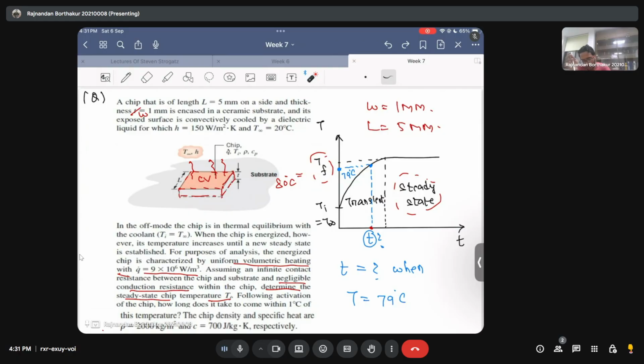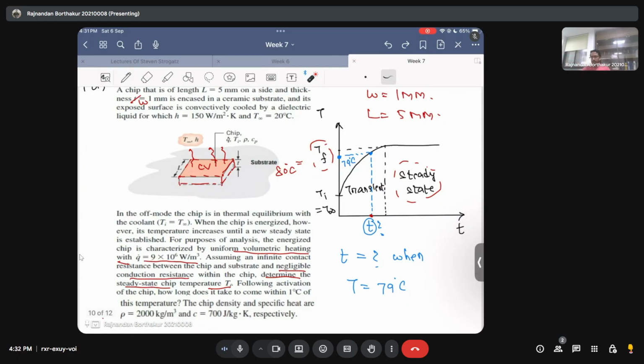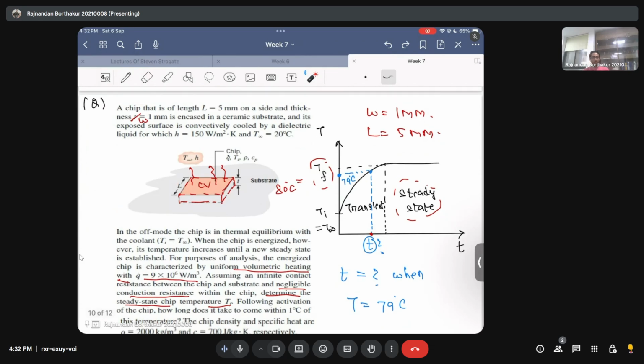All right. Then this is what we did. So I didn't touch one concept, which is known as the semi-infinite solid, which is another case of a transient body. But here, as I said, in case of a semi-infinite body, you cannot neglect the spatial variations within the body. And actually this is true for Biot number very much greater than 1.